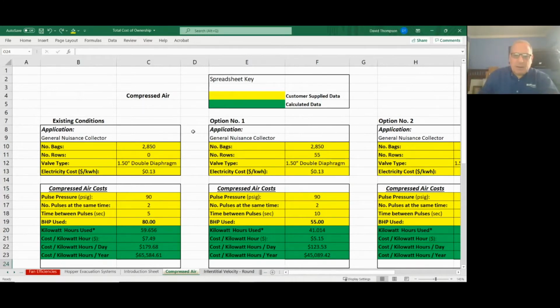Now, typically, a standard felt bag with a Precoat on it will have to pulse more frequently. You cannot run a differential pressure higher, so that drives you to pulsing more frequently on demand. And the reason we recommend on demand is because you don't have this unnecessary motion that you're going through with this baghouse. Systems that pulse on time quite frequently pulse too frequently and will pulse off all of the Precoat that you've seasoned on the bag and got it to work effectively, and now you've pushed it all off. So you've got to reintroduce that and get your baghouse back in good operating compliance.